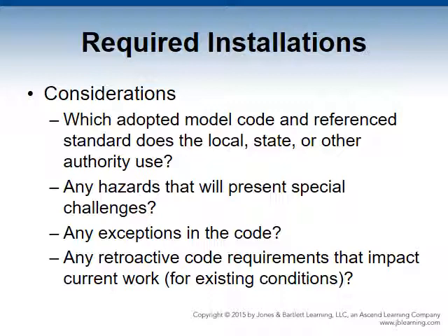For existing conditions, determine if there were any retroactive code requirements in effect at the time of construction and reference them. Knowing when a building was constructed, and the code requirements at that time, is critical to evaluating an existing system.